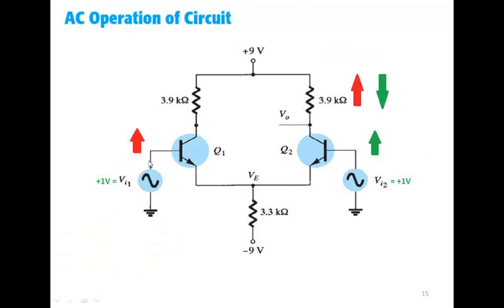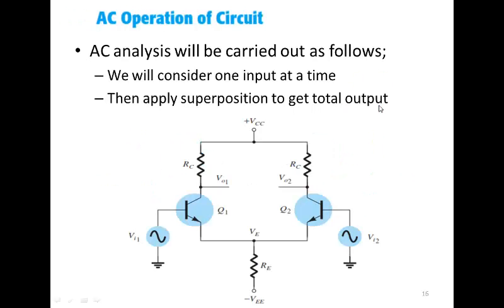Similarly, in this slide it is showing that if input is increasing at V1, output would also increase, and if input is increasing at V2, output will decrease. So for one terminal it is showing an increase in output, and for the other terminal it is showing a decrease in the output. So for this, gain is positive, for this, gain would be negative.